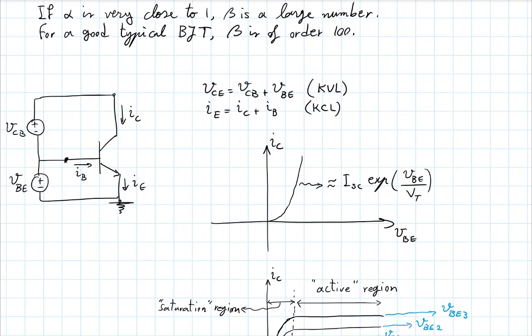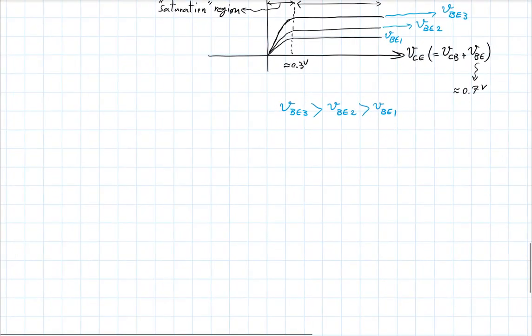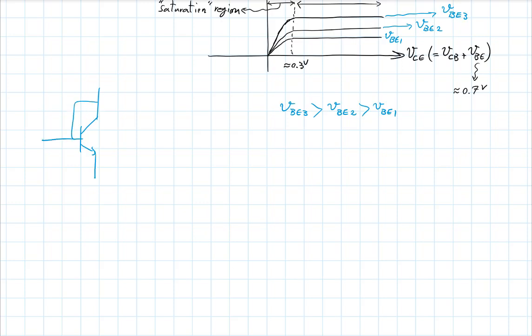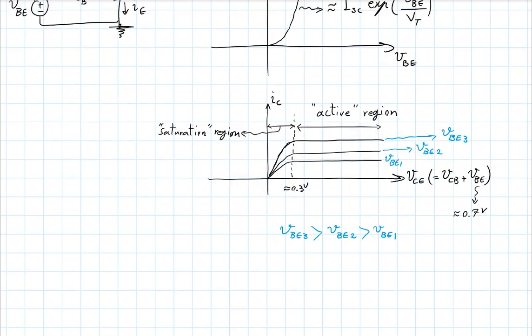Yeah, connect the base and the collector. This is a diode. If you do this, that's a diode, because now you don't need this extra pin. So if you put this in a package and sell it, that's a diode.